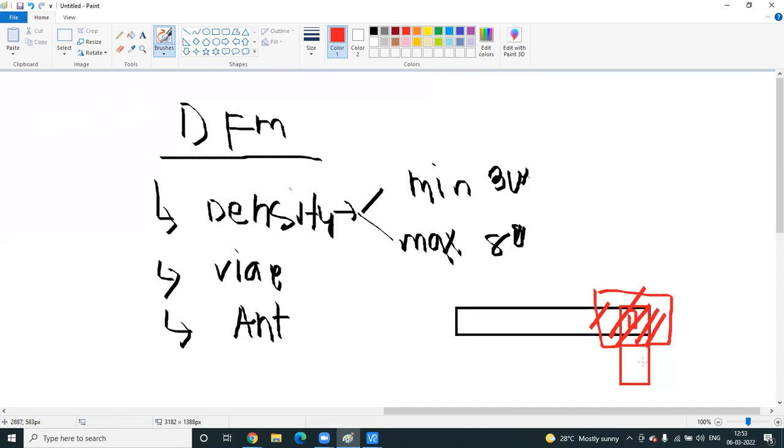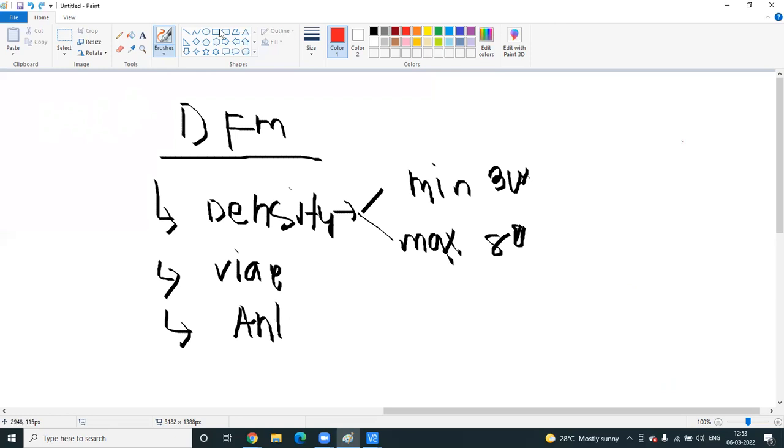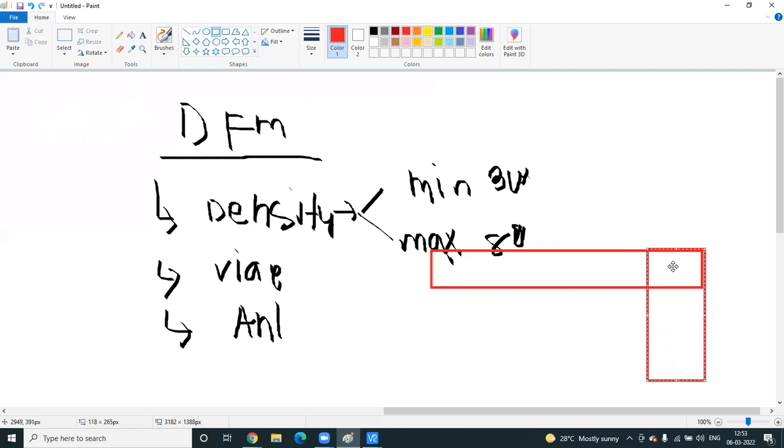This much big contact, or you are using some very small one. This size is 0.5 micrometer. But you are using a very small contact, and contact also will carry current. So EM also will be a problem. So this will be caught in the DFM stage. Contact enclosure, density error, antenna error. So now we'll discuss antenna error.